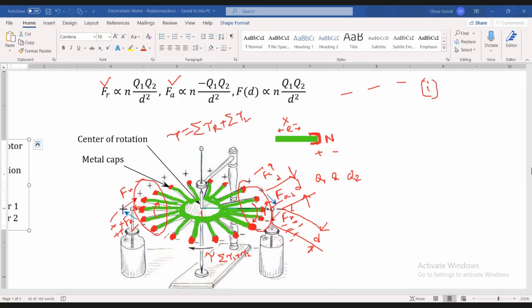But for the rotational motion, it's not that much use compared to the linear type, because there are several rotational motors available and we can get precision angular position from any hybrid stepper motor, or we can also apply the microstepping and the advanced switching technology to obtain more precise angular position. Therefore, this type of electrostatic motor, that is the rotational type of electrostatic motor, is not that much used, and it is not commercially used.